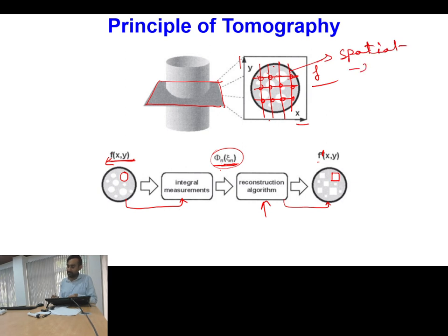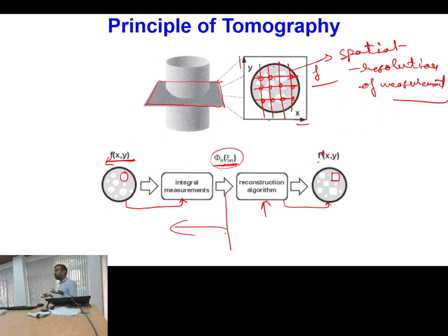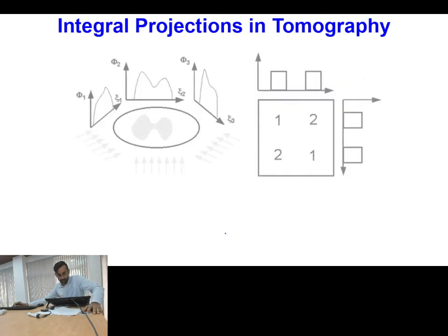Okay, so that is depending upon the spatial resolution of measurement. Is this one clear? So it means this is a two-step method. In the first step, we measure the property whose value we may think will be different for liquid and different for gas. And in the second step, we use that information of the data available at discrete points to construct the phase distribution. Okay, so that is nothing but my reconstruction algorithm. So this is a two-step procedure.